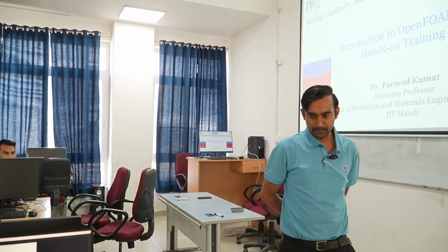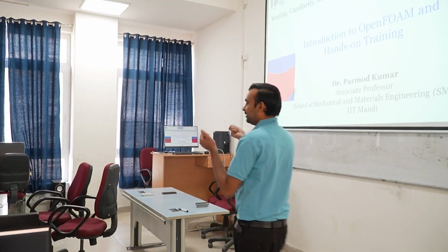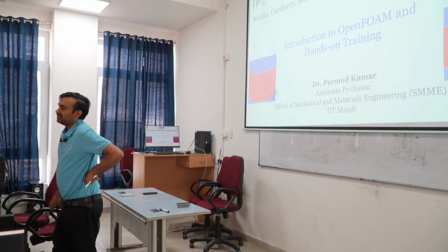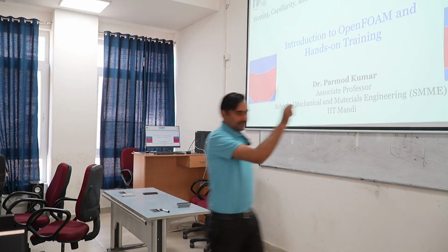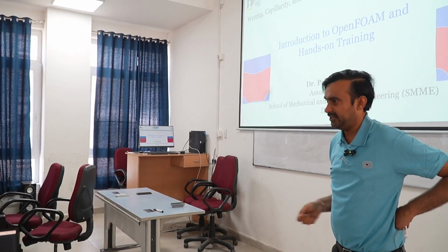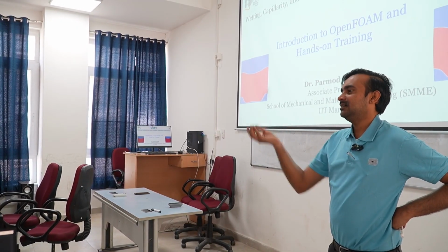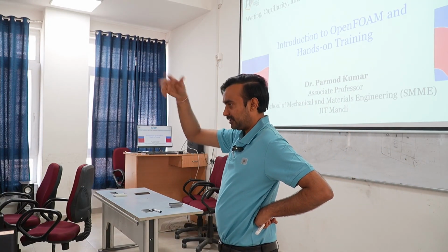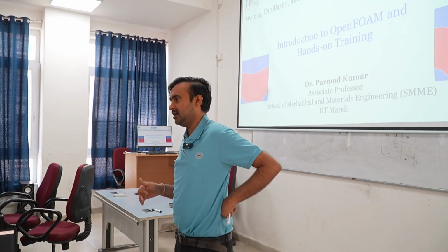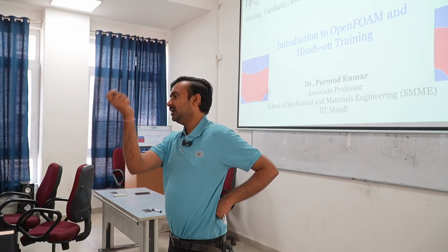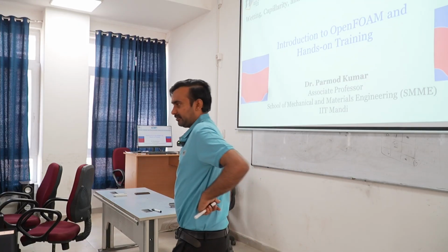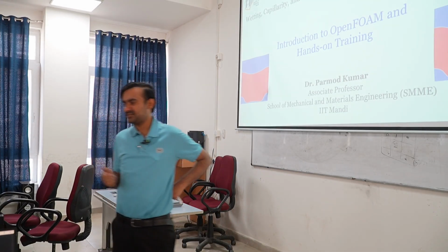Another important point is, many times whenever we solve a problem in a standard equation, I want to do small tweaking. Say I have surface tension implemented in the standard solver in a certain way, but I found that in the situation I am having, surfactant is present at the interface in the physical phenomenon. If surfactant is present, then ultimately my value of surface tension will not be constant at the entire interface. At different portions of the interface, the surface tension coefficient will be different.